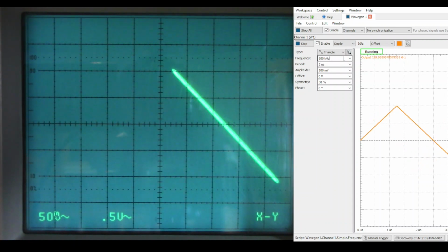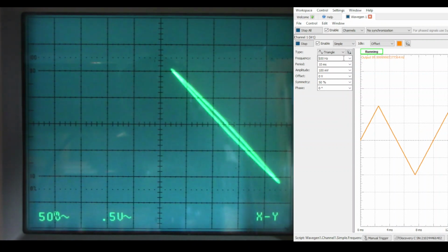And now if we go down, we can see everything is pretty good. Here we're at 500 hertz, 200, 100. You can see it's starting to open up again because we're having some phase shifts. And if we keep going, the signal is going to get smaller as the output amplitude drops. Another way of saying that is this amplifier is acting as a low-pass filter.